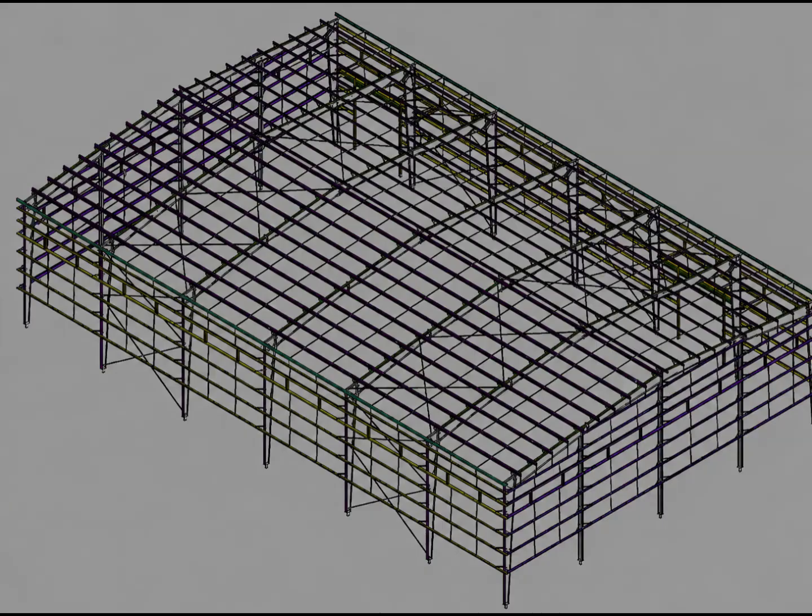Now move your attention toward the roof. The roof contains a repeated arrangement of primary and secondary framing members. We can see the main roof framing members and the numerous purlins arranged across the roof. This creates the dense grid that is clearly visible in this model. The purlins follow the roof geometry and are repeated from one framing bay to another. This repeated arrangement provides the background against which the sag rod arrangement needs to be understood.